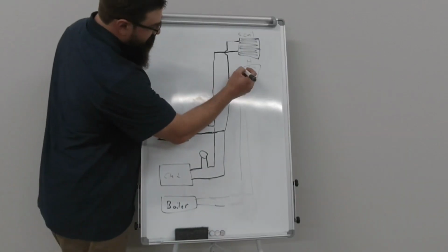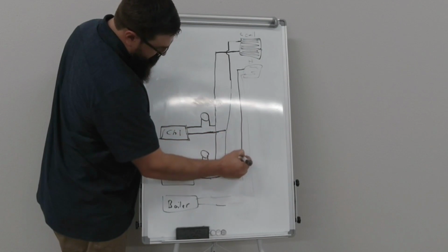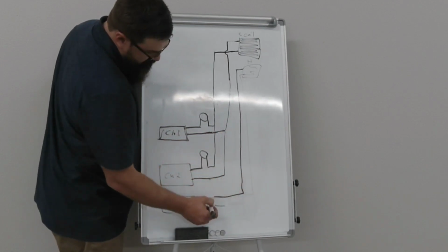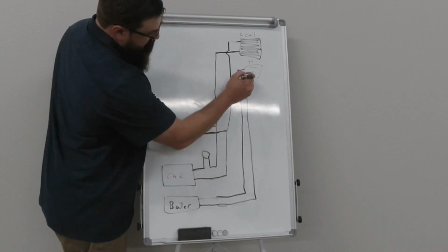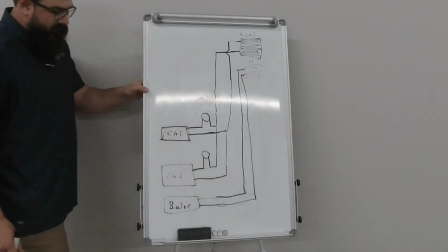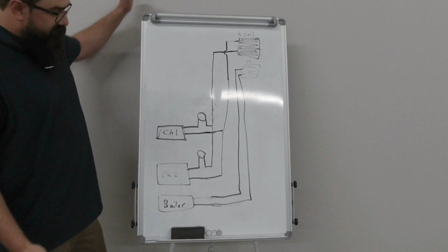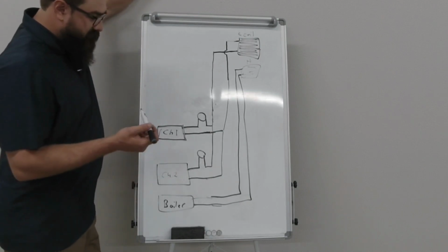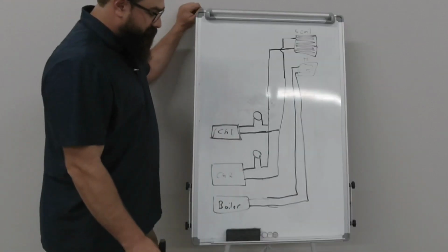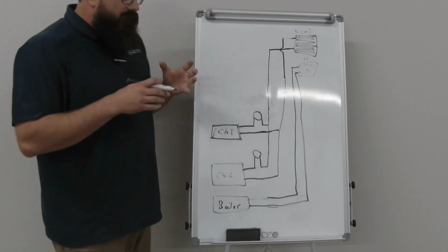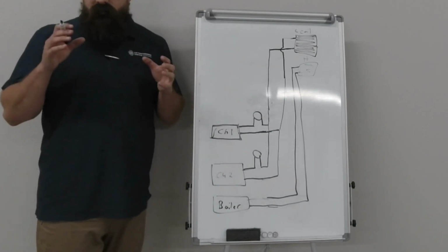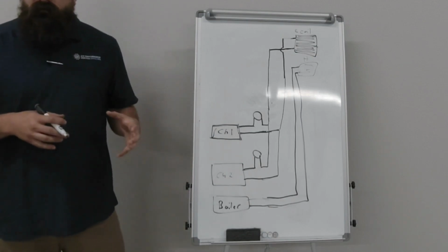As we were saying, this is your basic 4-pipe system. 2 pipes for each piece of equipment, or each process, I should say, heating and cooling. Then we got into dedicated header versus common header. Basically, it's either your pumps can do either chiller, or your pump only does one chiller or the other.